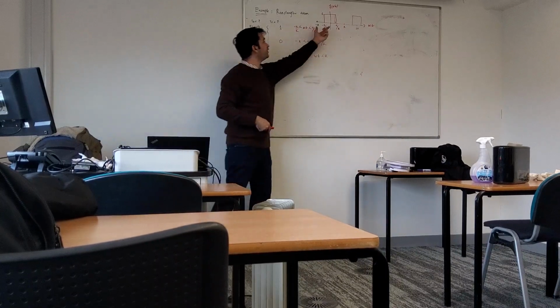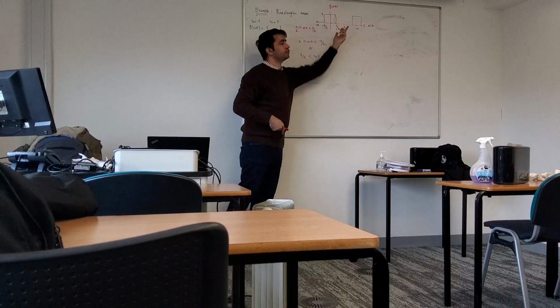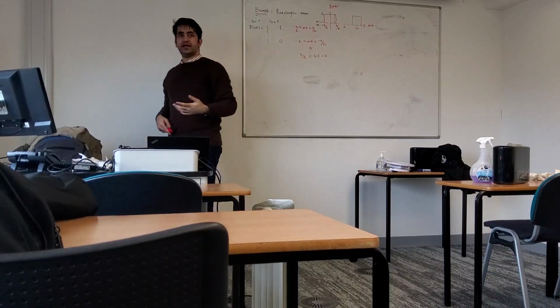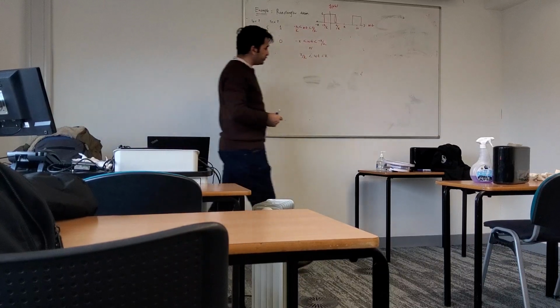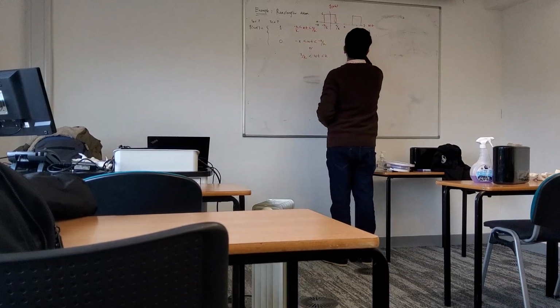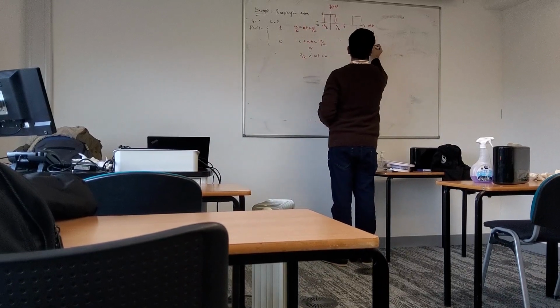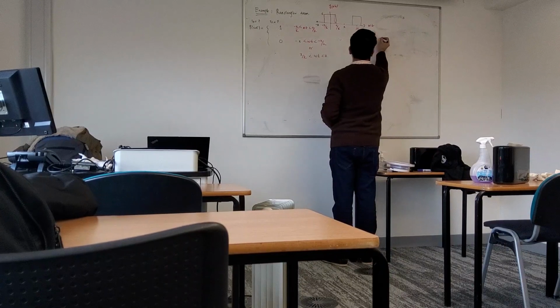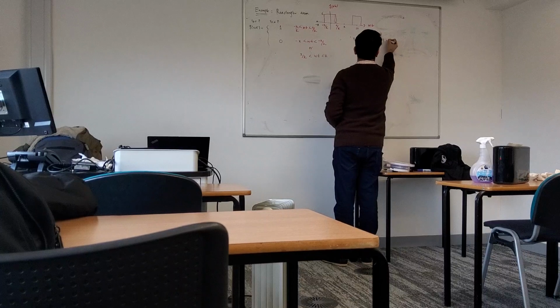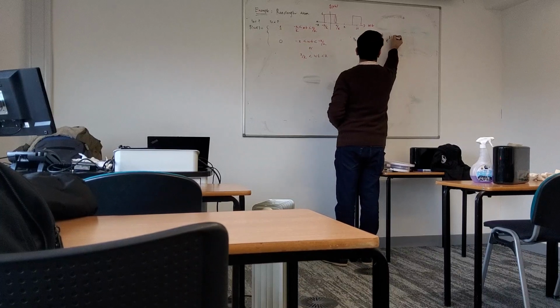So it means that it has value only here, whereas at this portion it's 0. And to find Rn, what do we do? We have Rn equal to 1 by 2 pi, integral from minus pi to pi of f of theta e power minus j n theta.